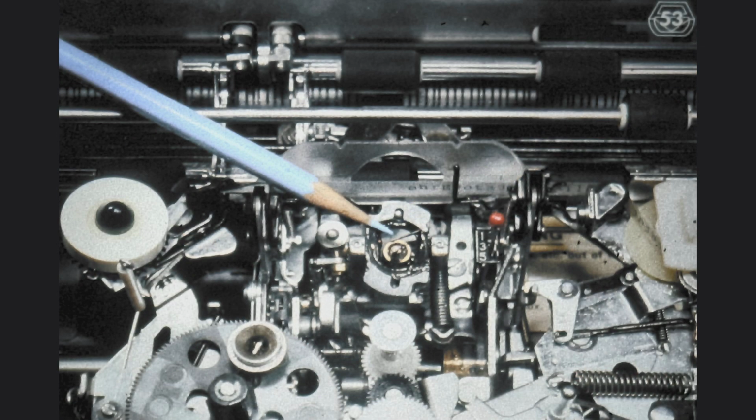If your machine comes equipped with a new style tilt ring, you will find that there is a spring in it which tries to move the upper ball socket toward the front of the machine, toward the keyboard. This feature allows the rear portion of the tilt ring to make constant contact with the inside wall of the type element, so that when the machine prints, there is always solid contact between the tilt ring and the internal wall of the element. This is one more of the features aimed at improving the reliability, the durability, and the writing picture of the IBM Selectric Typewriter.